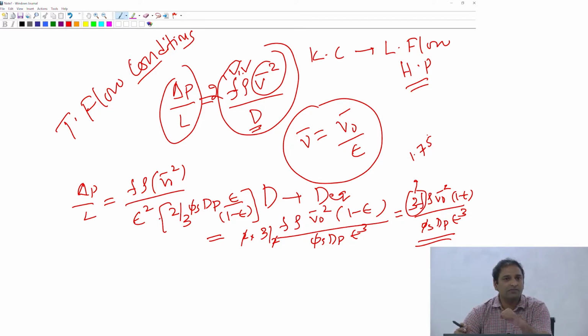They fill cylinders in the packed bed, they fill ball saddles, spherical balls, and then you make sure that your Reynolds number is greater than 1000. So we said for the flow of fluid around a particle, anything greater than 1000 up to about 200,000 was the Reynolds number range for which the conditions are turbulent.